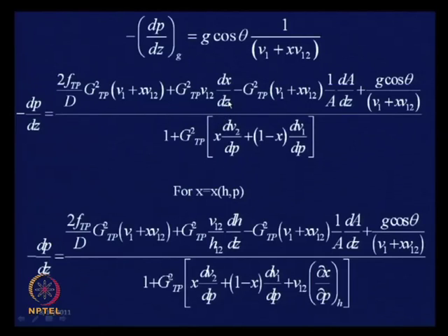In this case quality is a function of enthalpy as well as pressure, because it is not a function of only enthalpy, which could be obtained from the heat balance equation. When there is flashing, then apart from enthalpy balances, the pressure gradient also comes into being, and under such circumstances the momentum equation or the pressure gradient expression becomes slightly different.